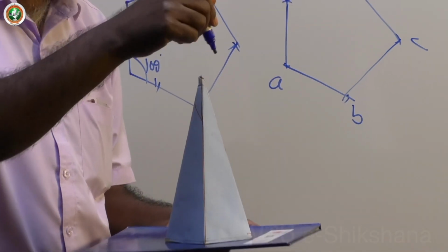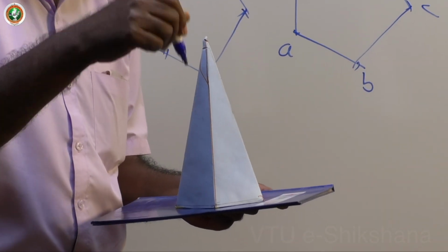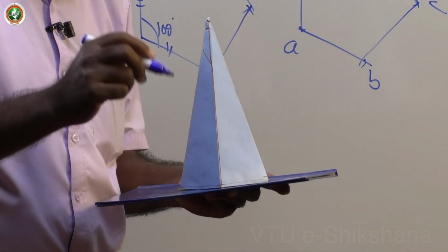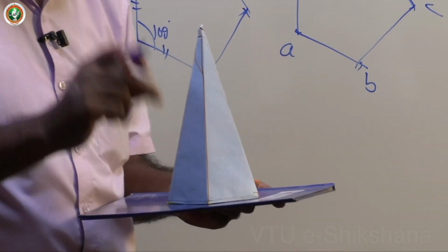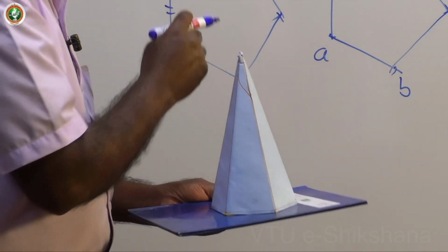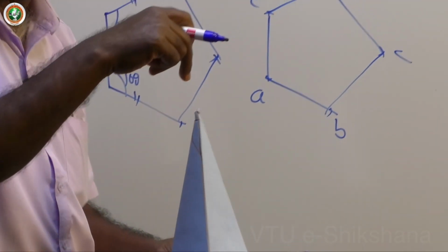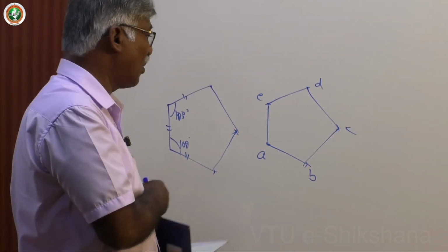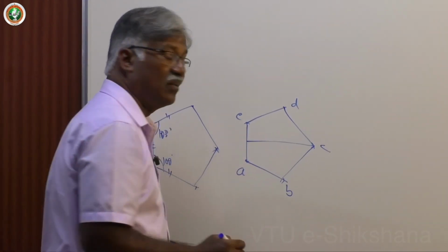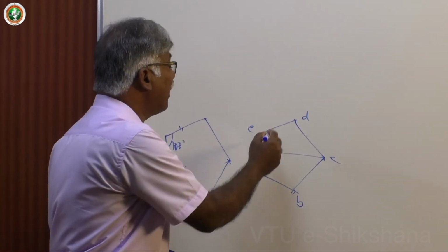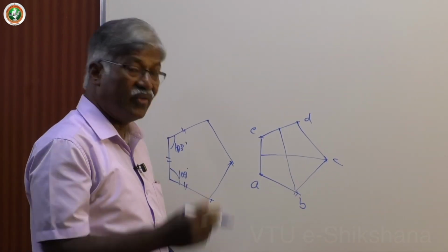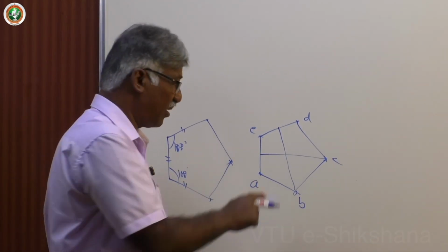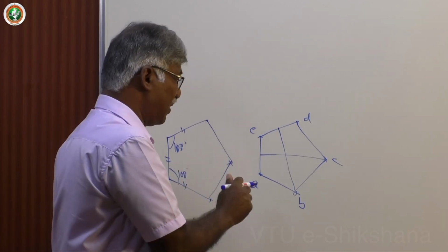Now if you look from the top, you will get the top view as a pentagon, even though the base is not visible, the boundary is visible, since the edges of the base and slant face edges are common. So that is why this is visible. Next, what about the top view of the slant edges? To identify the center, you have to draw two perpendicular bisectors, preferably one horizontal and any other one. Even in the computer you have to do this, it never gives the center automatically, it gives the pentagon, not the center. You can identify the center, but you have to draw all these.